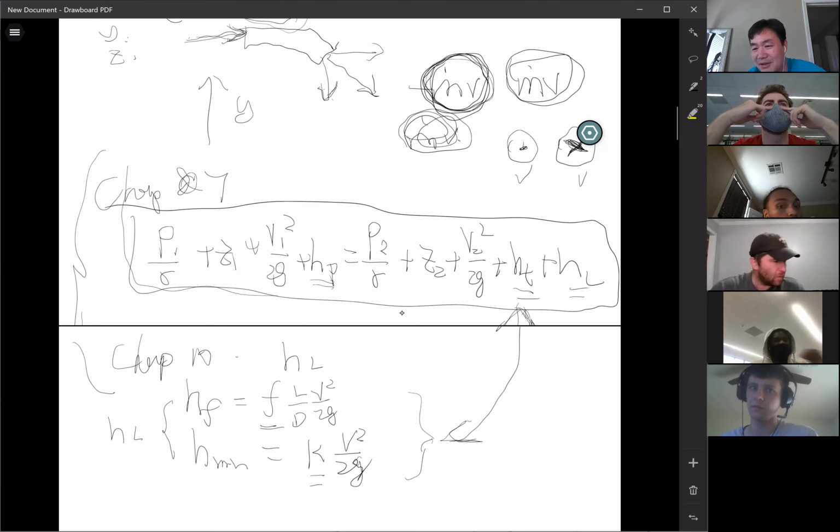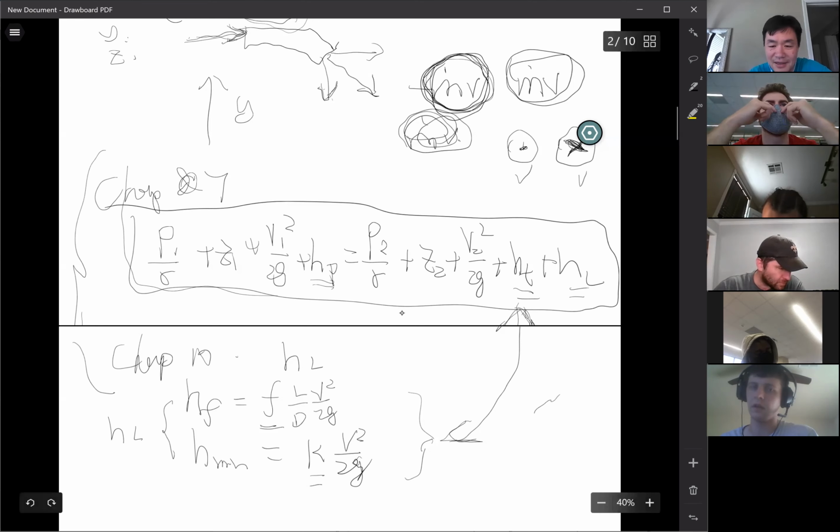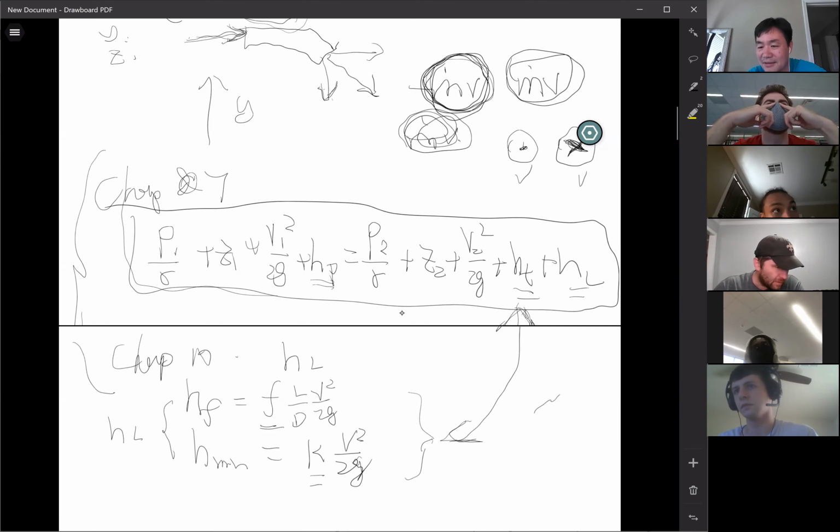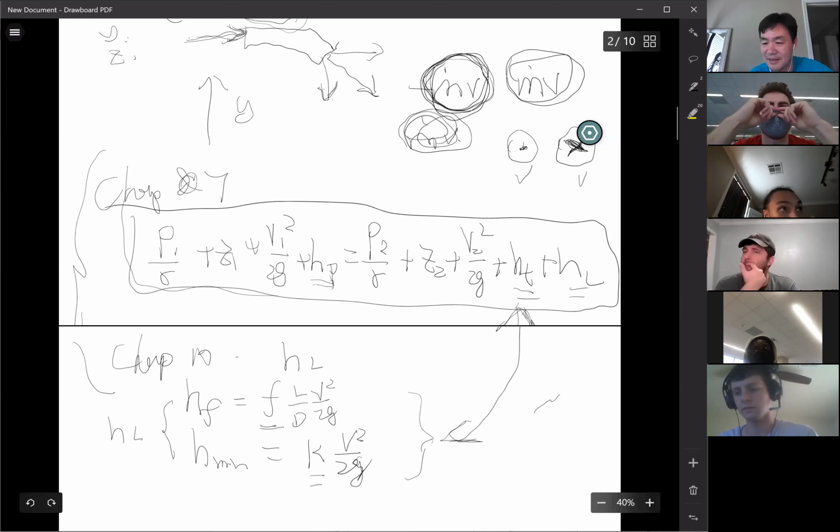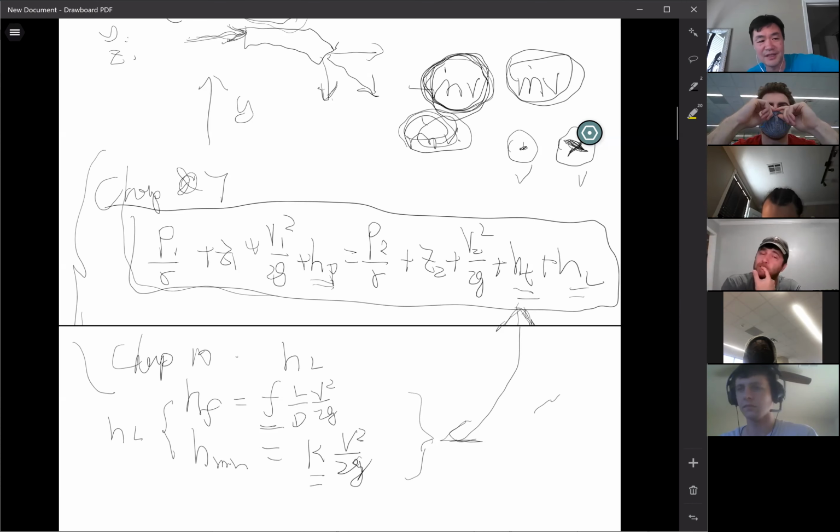If you buy a pump or a turbine, these are the specs from the company. But the loss really differs from different situations: from the pipe lengths, velocities, from those fittings, and that can have a lot of variations. So you probably need to know how to calculate that.